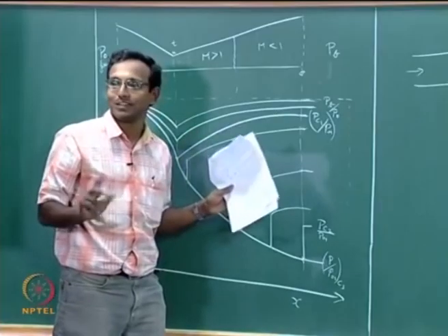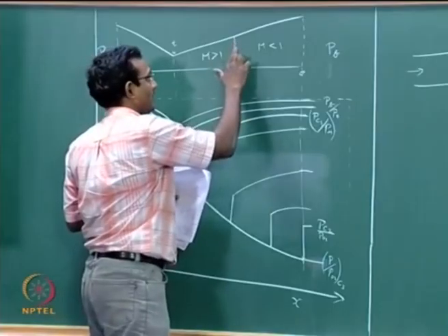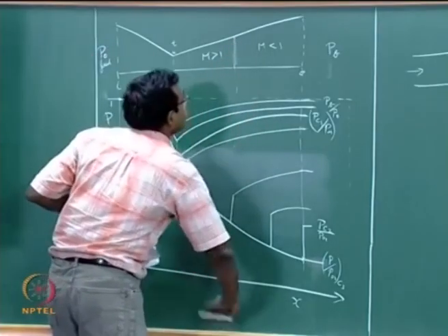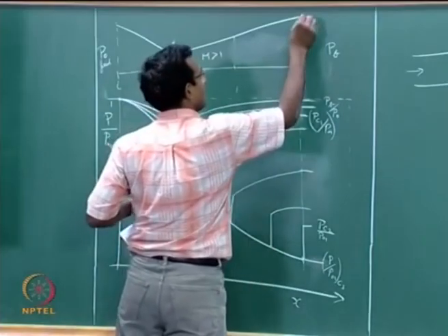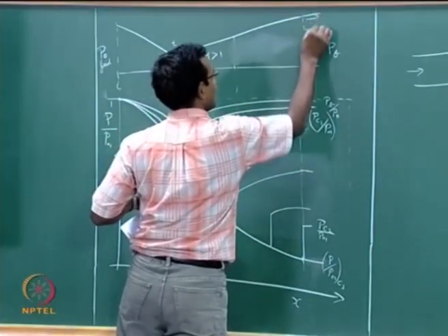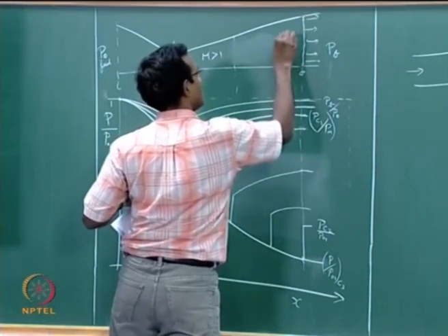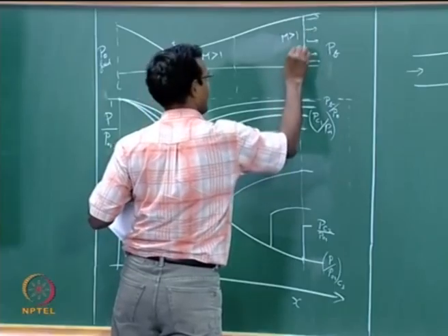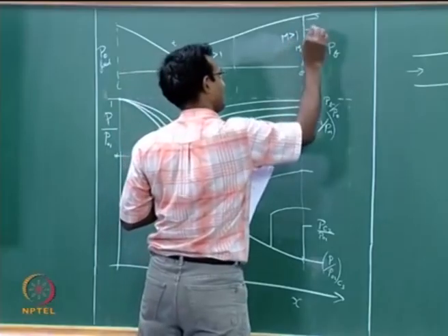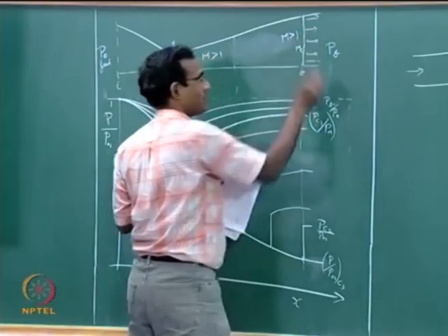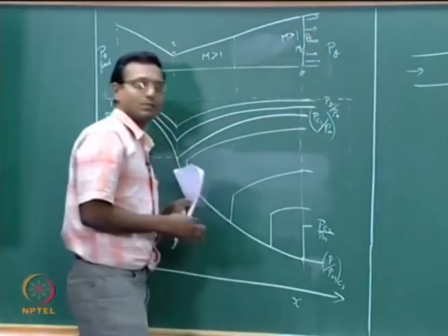It is all matched perfectly nice, it is just going to sit there. So the full flow inside, now we are at the exit, shock at the exit. I will rearrange this again. Shock at the exit, I am going to assume 1D flow, so the flow is going to go straight here. In this region there is a shock, here it is M greater than 1, in fact M equal to M exit at that shock location, and I am going to have subsonic flow just after the shock, and the pressure is matched, P exit is equal to Pb.